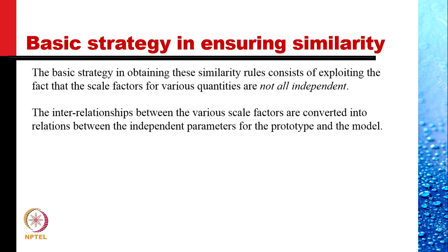And here we state that the basic strategy in obtaining these similarity rules consists of exploiting the fact that scale factors for various quantities are not all independent. Like we have seen, the scale factor for area Ka is equal to Kl squared. Ka and Kl are not independent. Similarly, the scale factor for volume was seen to be Kl cubed, not independent.